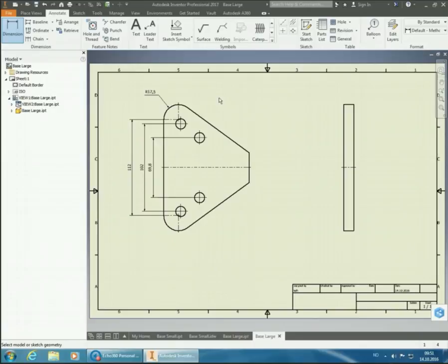And the fact that we are putting the radius on one side and we have a symmetry line, it means that we have to have that same radius on the other side. So it's not really necessary to put typical behind it or put dimensions on both sides in this case. So then we want to put in a couple of length dimensions so that we can move over to this side. So we'll do the length from the end here and to the center of the first hole. We don't need to give the length to over here, because that's given by the radius already.